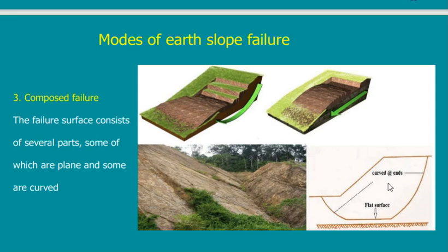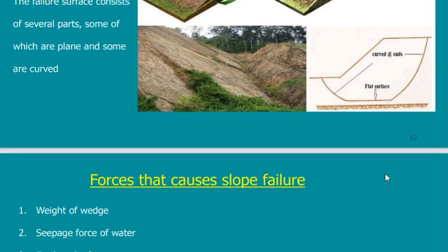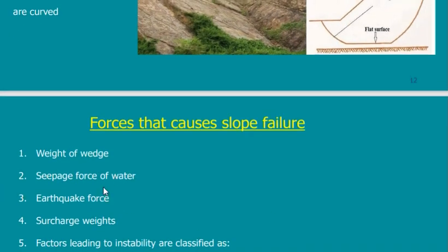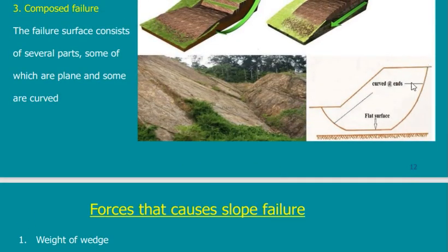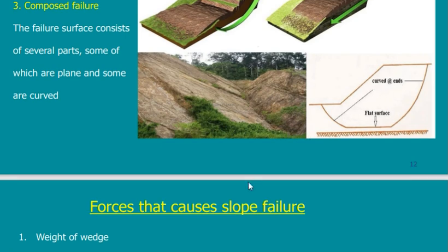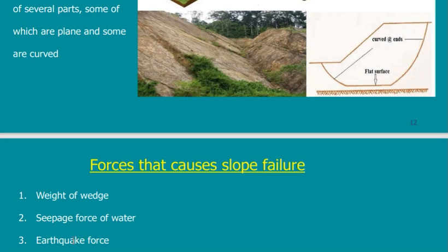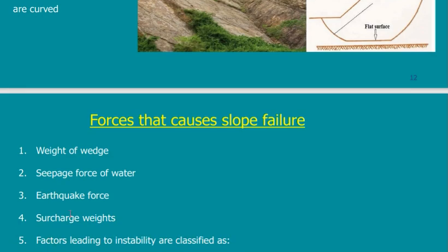Of course, here I am speaking about the own weight of the soil itself. Increasing the own weight will increase the driving force. Seepage of water: if I have water here and the water is going down, it is pushing the soil in the same direction of motion, so it will help in instability of this portion. Earthquake: any earthquake can cause failure in any building without discussion.